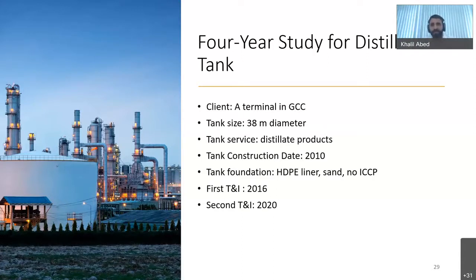It's a 38 meters in diameter tank constructed in 2010 on crushed stone ring wall, clean sand, HDPE, and with a release preventive barrier. The tank leaked after 6 years from construction date. So in 2016, the tank leaked, and it had to be taken out of service for inspection and repair.